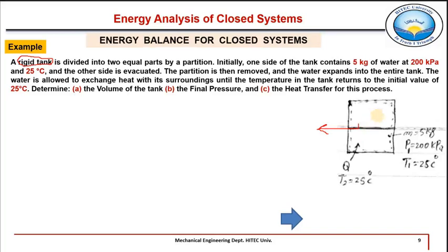So when it takes heat from the surroundings, initially what happened is that when the partition was removed, water was allowed to expand, volume was increased, pressure was dropped, and there was a tendency for the temperature to drop also. But as the temperature drops, water absorbs heat from the surroundings, and the initial temperature is again attained. So that is what is written here.